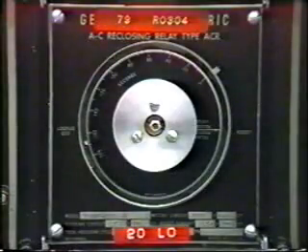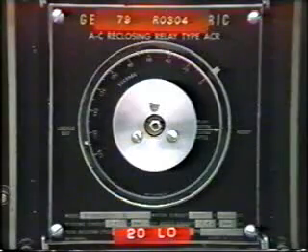However, on transmission and sub-transmission systems, it's clear that reclosing schemes can help retain stability of the system and reduce the likelihood of generators or parts of the system falling out of step. But unfortunately, instability can and occasionally does occur. In the next segment, we'll be looking at protective schemes to assist the system in such instances. For now, switch off the tape and thoroughly review this material in your workbook.